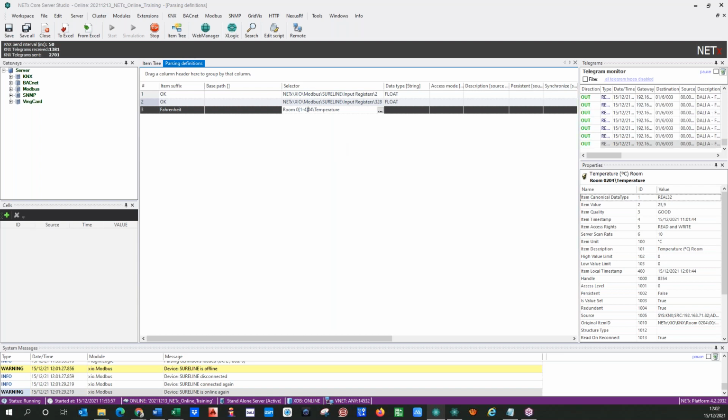This is the floors in this alias that I have. In reality, we only have 2 floors, but we created alias for the other floors, 3 and 4. And the last number, again, it is from room 1 to room 4 between brackets. And just take care with this because the backslash has to be written double again, in this case also.